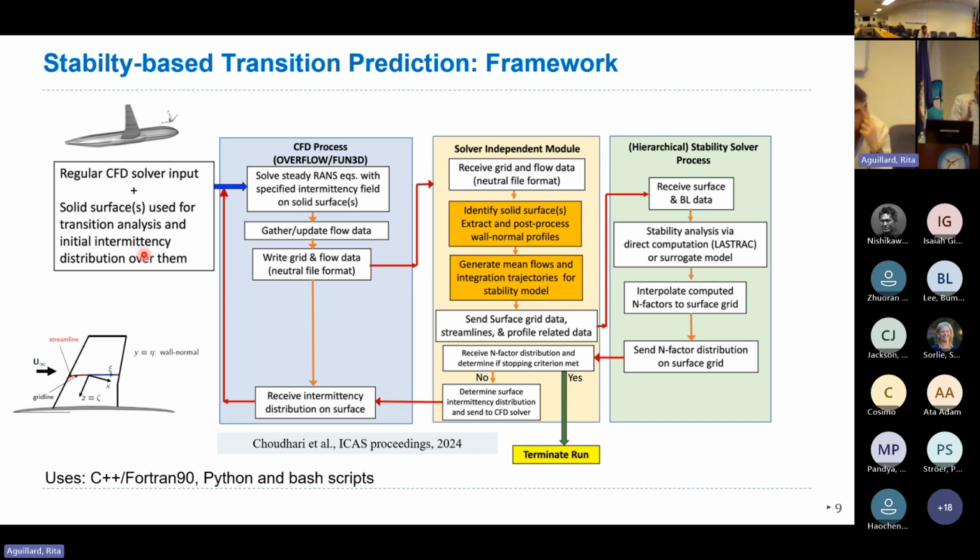So you try to delay transition, right? We don't have as much laminar region. So based on your prior experience, or if you don't have any experience, just set it at the most, say 3/4 of the wing chord, if you think it can achieve laminar flow. Sometimes that might be too large because you might have an adverse pressure gradient, and the flow might separate if you try to achieve laminar flow, but this iterative process will help you overcome that. You can use some physical insight to set where your initial transition location is, or you can just randomly set it initially, and the process is robust enough that it'll recover from that and fix it.